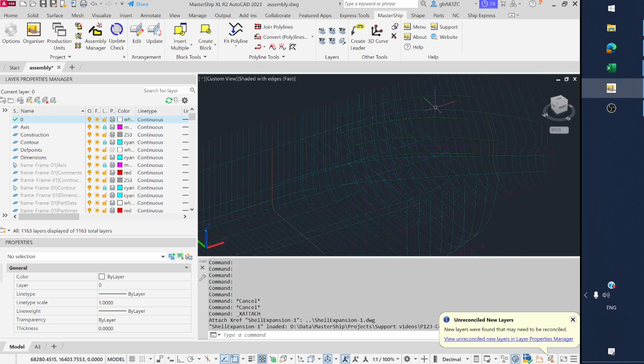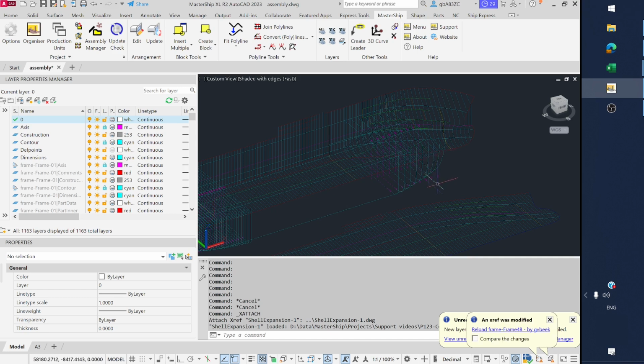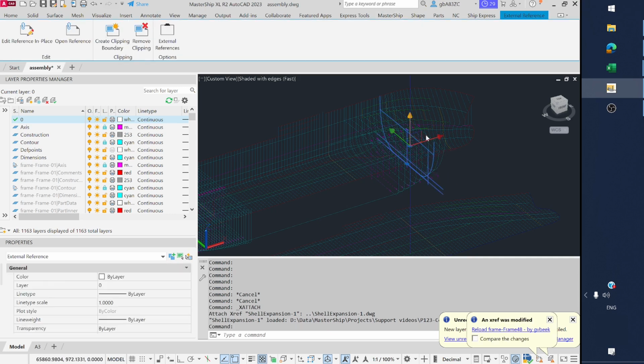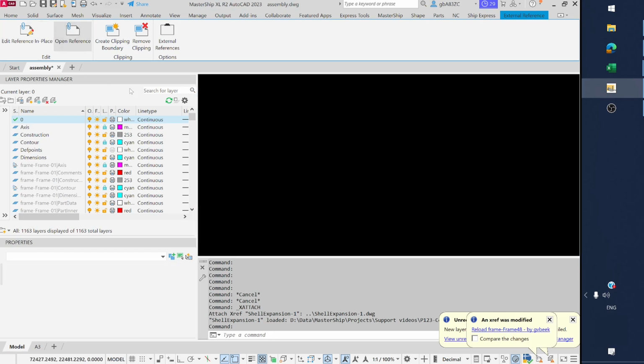It can also help to, for example, indicate seams and butts. So here we see a seam, and also here, which should be considered in the 3D construction model. So this is a nice way to visually check if everything is consistent. So let's make some basic construction elements. I'm going to start with this frame here on the bow section.